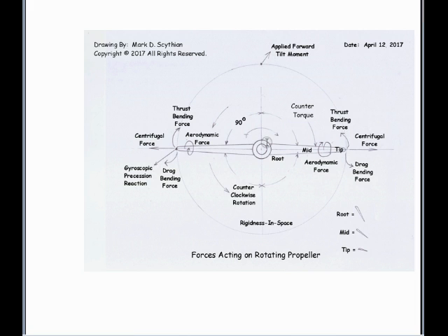this means the applied force would have to happen to the right at this point here. But for that to happen, there would have to be a cyclic pitch control, which causes the pitch to increase more on the left advancing blade higher than the retreating blade, causing a tilt to the right applied moment, thus causing a precession reaction. So that is all in the swash plate scissor links on a rotary wing or helicopter application, which exploits gyroscopic precession for main rotor tilt control.